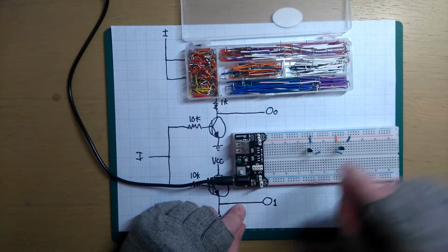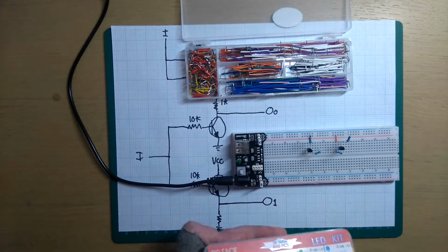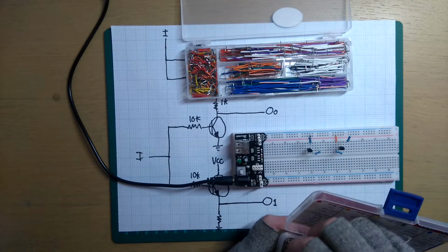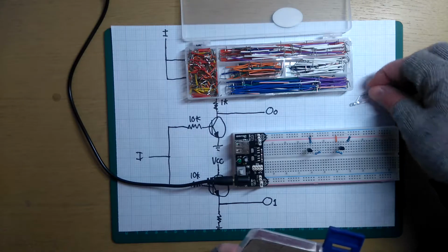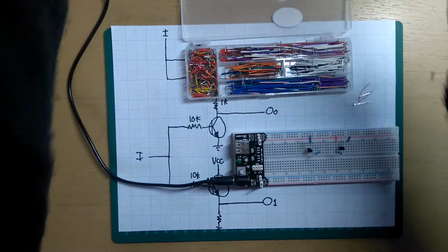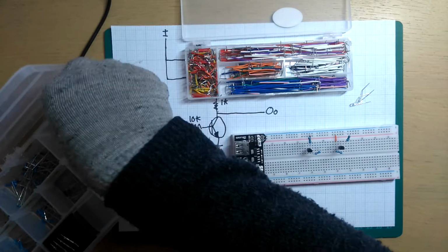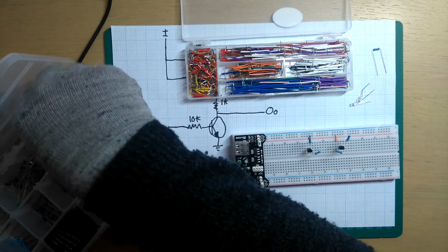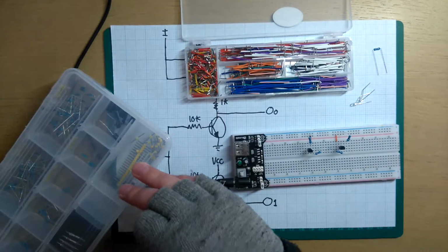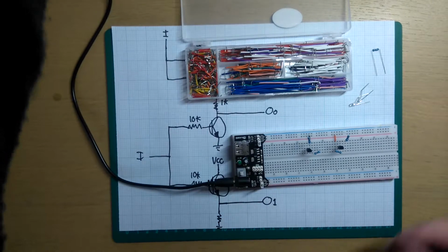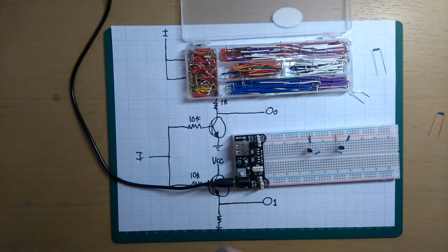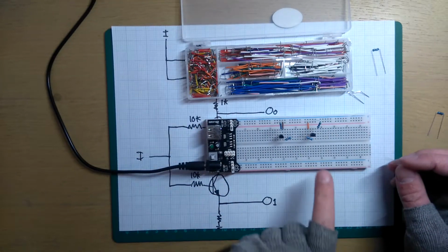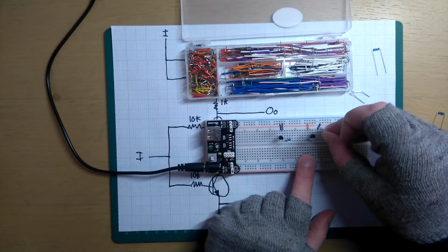Need to grab a couple of LEDs so we can actually see the output. That would actually mean I need to grab some more resistors as well. Let's do some red ones. Don't use red too often. And a couple more. We'll just use 1Ks for this as well, so it's not too bright. Right, there we go. So our outputs for these, on the buffer, it's on the output here. So we'll put that there.